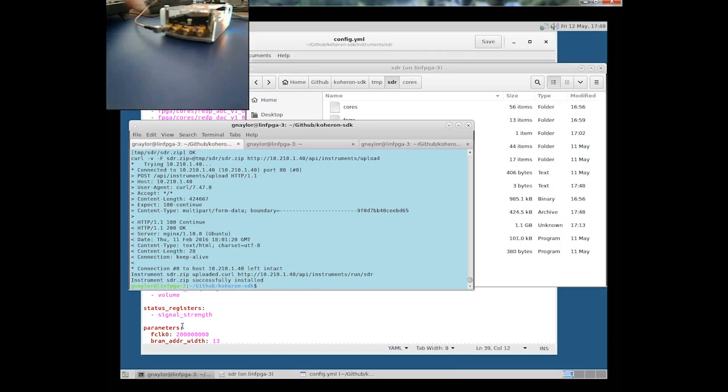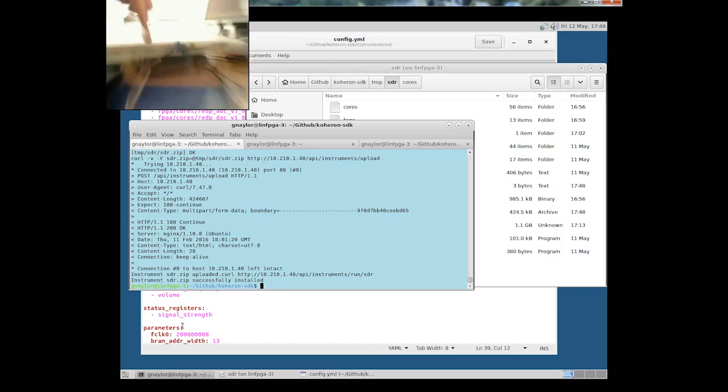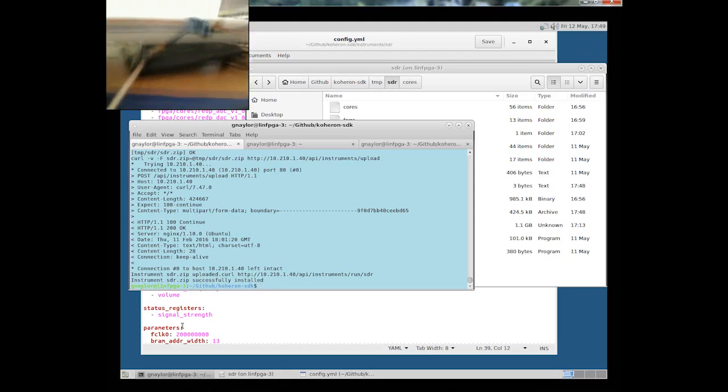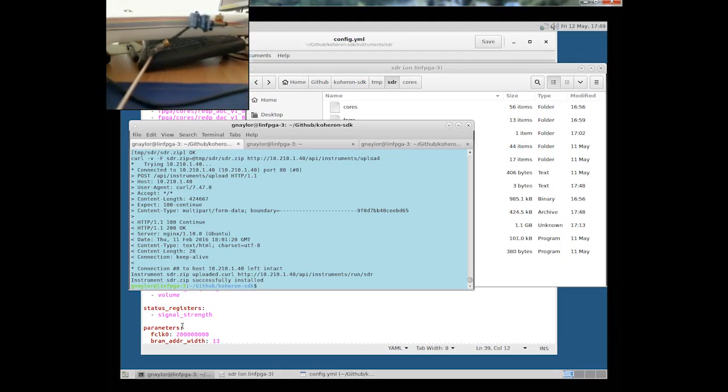So we see the RF input coming in here from an antenna that we built just here. Now the antenna uses some ribbon cable, which is constructed using some IDC connectors here. This is 10-way ribbon cable, and we've separated 9 ways off onto one side of this connector and 9 on the other, but staggered so that we have 10 turns in total,